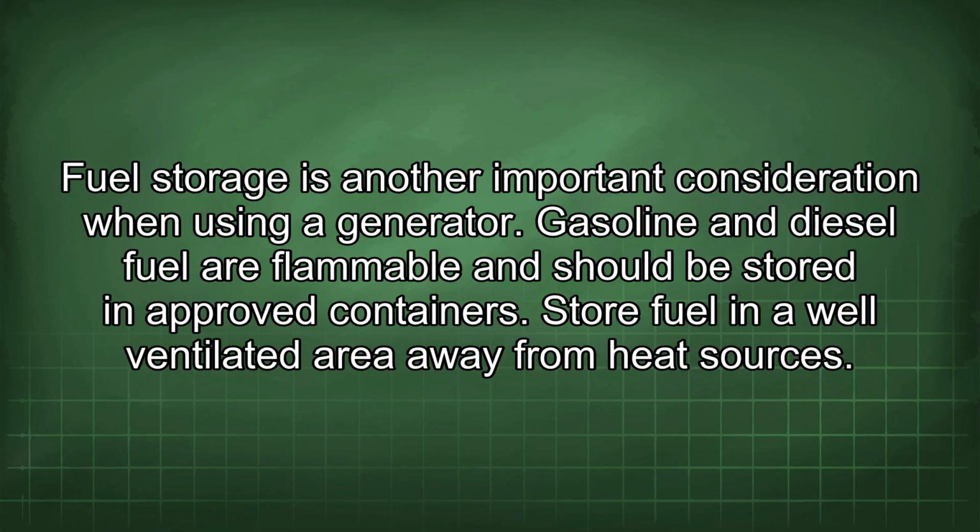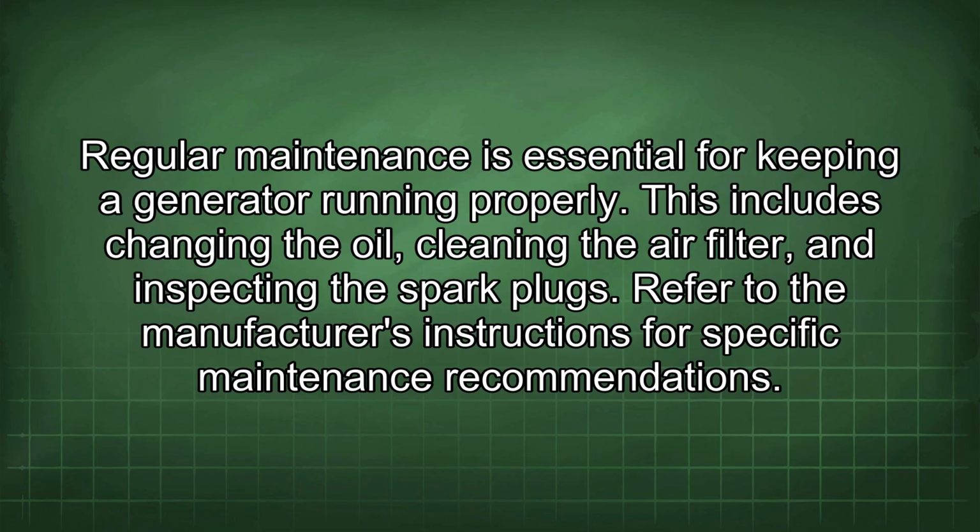Store fuel in a well-ventilated area away from heat sources. Regular maintenance is essential for keeping a generator running properly. This includes changing the oil, cleaning the air filter, and inspecting the spark plugs. Refer to the manufacturer's instructions for specific maintenance recommendations.